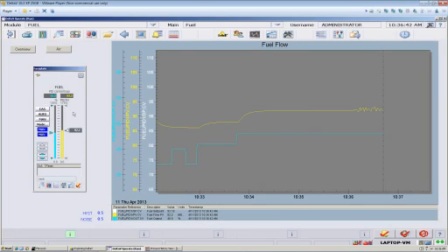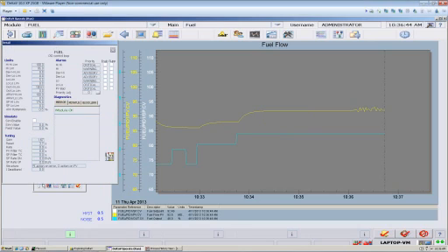The first thing I would do when you're tuning is check your tuning parameters. Oftentimes, PV filtering is added to filter out and average the effect of this noise. I don't want to see the effects of my filtering. I want to learn the true dynamics of this loop. So the first thing I'll do for my test is make sure that the PV filtering is turned off.